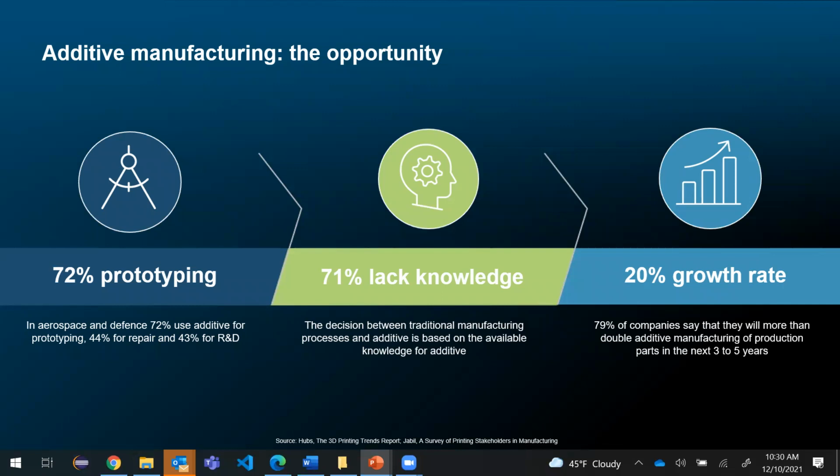Okay, so what you're seeing in the aerospace companies today with AM, which is a major driver for the high end of additive manufacturing, alloys like titanium, is kind of a big thing. It's mostly about not really critical parts. An example is building a large plane, where you have brackets, things that are behind the scenes, and I don't really care how they look. They have certain specifications and frozen regions, but the rest of it can be done through functional design, right?